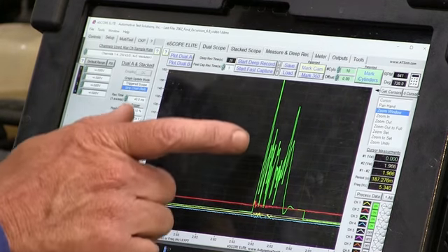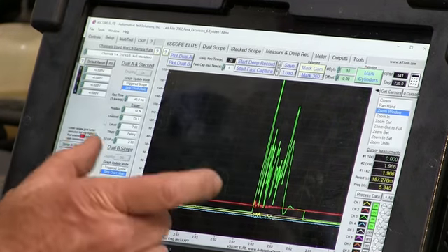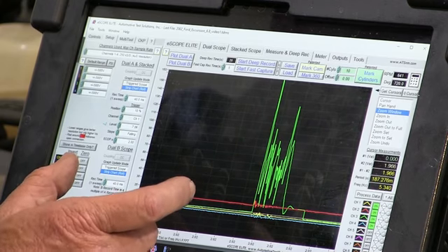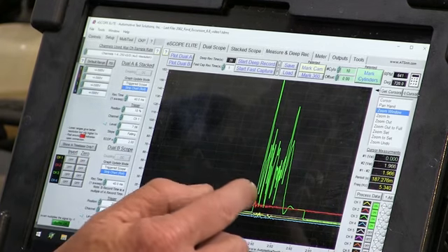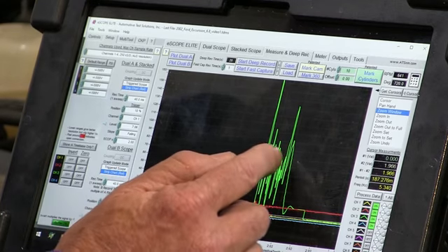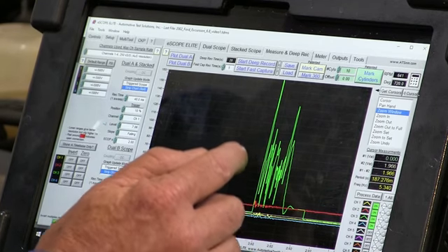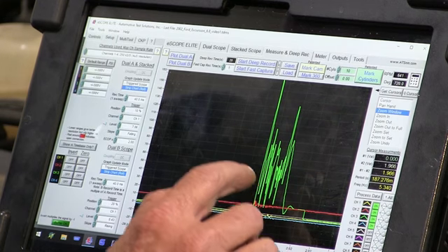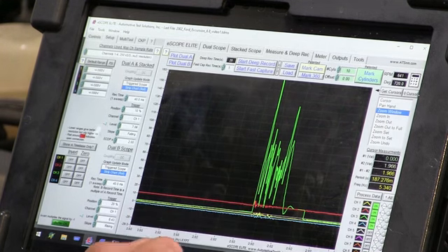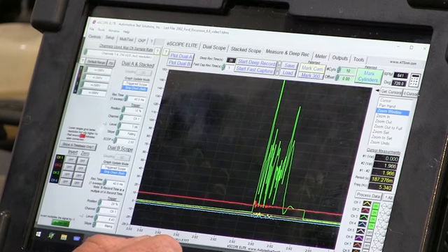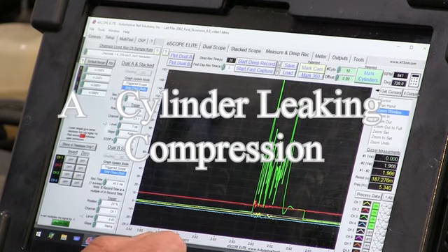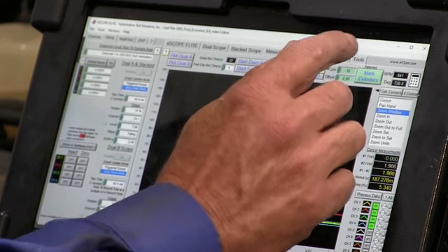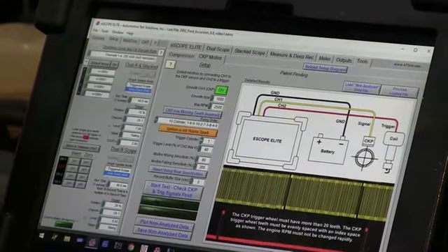Okay guys, look at how much turbulence that's got, because we got the throttle wide open, so we got a full load, a full compression pressure, and it's putting the coil under load, so that's arcing. Now again, I think that if we look at the amount of energy at the tail compared to how much turbulence I got, that's a carbon trace. But if you thought that that was a cylinder, we just cranked it and we had that problem, so we're going to rule that out. We're going to come over here.